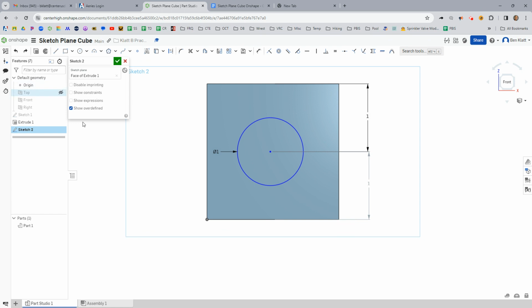Make sure that you don't have things there. Now, sometimes it will keep this grayed out reference for you. Let's undo that, get it out of the way, because we don't want those weird references in. Whoops, I blew it. Let's dimension again, and this time let's do the right thing, which was horizontally. And it doesn't matter whether you go top or bottom. And these are dimensions, they're not part of it.